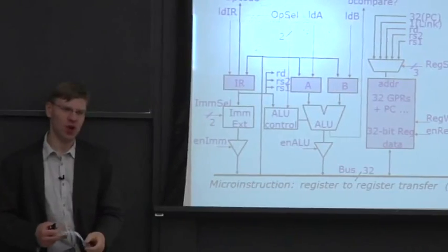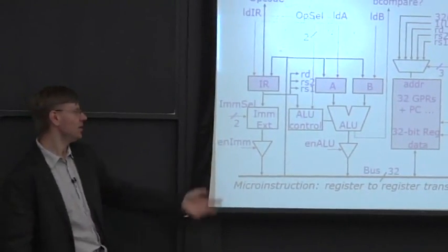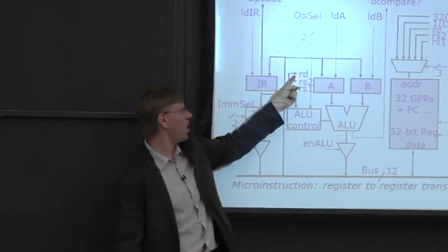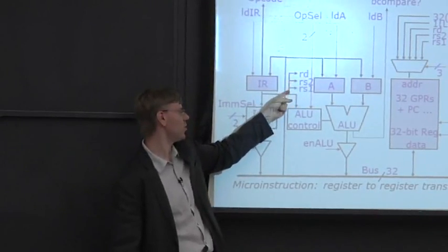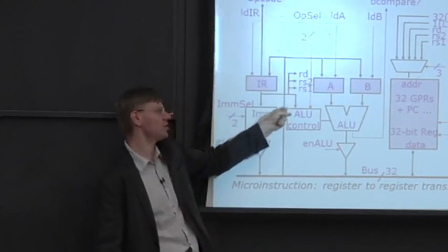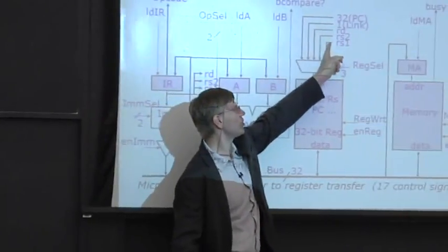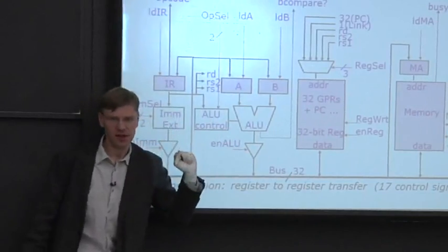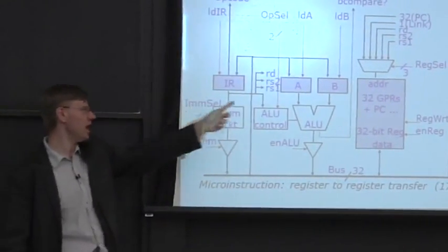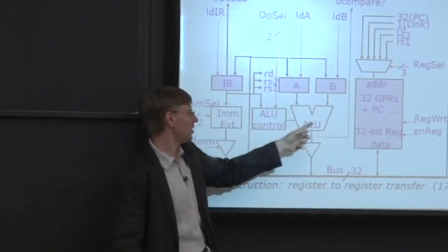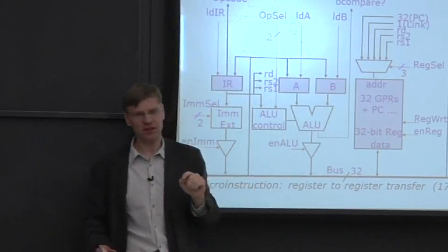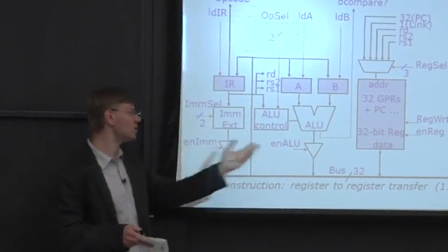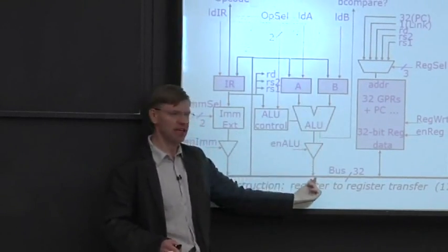The next thing we need to do is go get the actual operands. So in the third cycle here, we'll take the two sources, RS1 and RS2, and we're going to fetch first RS1 from our register file and latch that, or register that, into the A operand. Then we're going to do the same thing for RS2 on the fourth cycle. And now we can actually do, let's say, an add. So let's say we're assuming that we're doing an add instruction here. So now we can do the add. So we let A and B actually add.